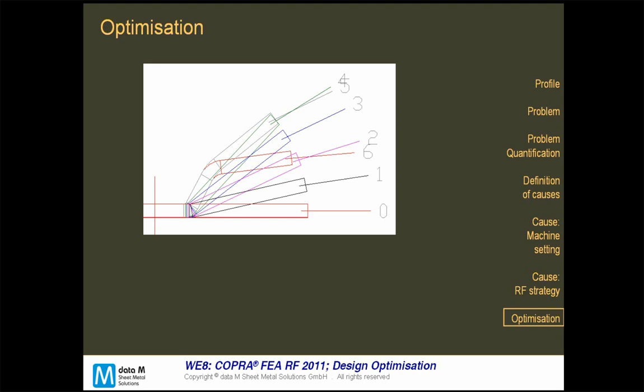In this case, the bending sequence was changed to a 1 bend forming strategy. The original was a 2 bend strategy, and we could see that the 2 bend strategy could not be used due to the punches making it impossible to get a nice material flow to the inside. Also, the bending calibration method of the inside radius was changed so that the material did not slip outside due to these difficulties to flow to the inside.